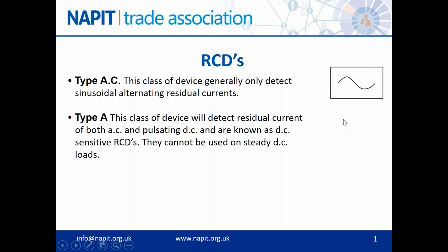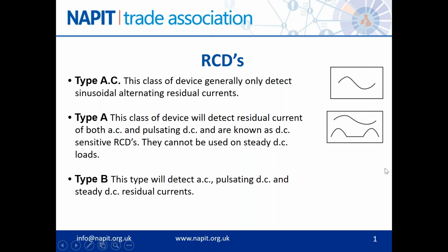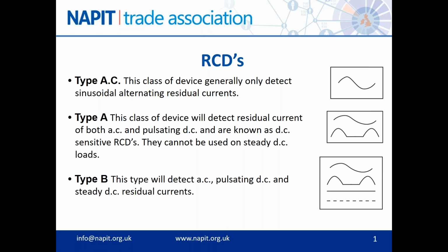What we are getting now is more equipment that has inverters in them. We're now fitting PV systems on roofs, we're fitting electric vehicle charging equipment. These use and generate DC, and manufacturers are often asking installers to install the following types of RCD, a type A and a type B. Please try not to get these confused with type B's, C's and D's circuit breakers.